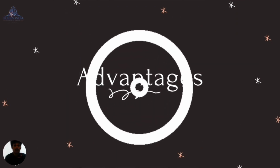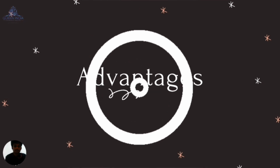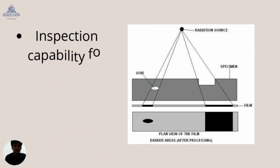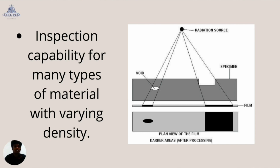Now let us see the advantages of radiographic testing. The first advantage is that we can inspect a material with varying density. Here in this picture you can see a material with various densities. And here the darker spots are produced on the film with respect to the density of the given material in the picture.